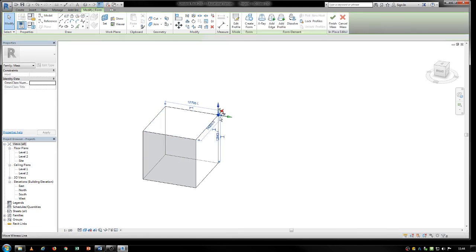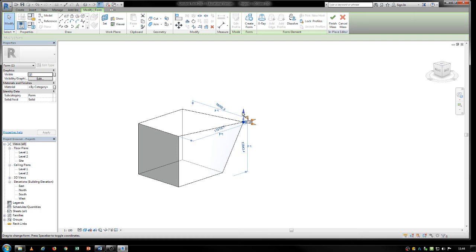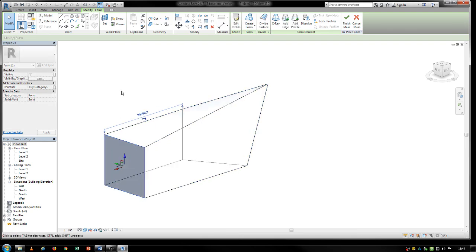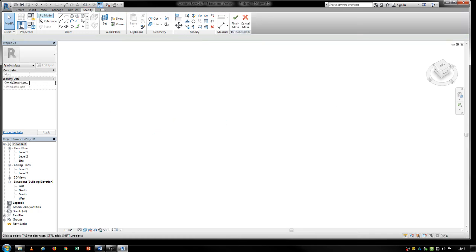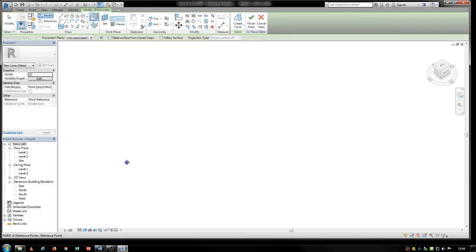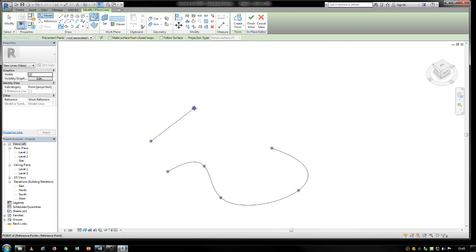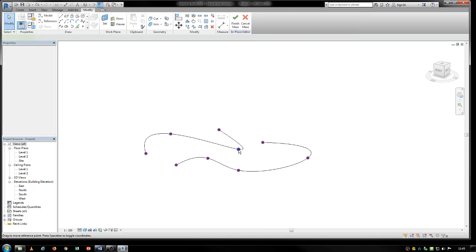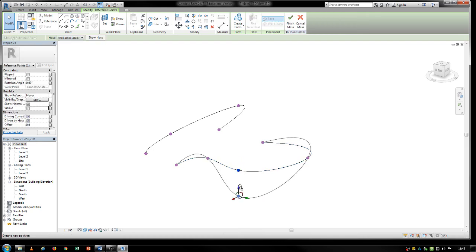It does the extrusion for me, then I can go in and pick points and move them around, or edges, or faces, and do the same thing. I could also, if I delete that and I'm still inside the massing environment, draw a set of curves here and a different set of curves there, and it's in 2D. I could also do them in 3D, so I move some of these up and down so that it has a 3D definition in it.